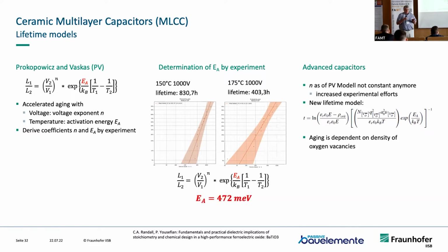And if you want to parameterize them, you have to do the experiments for 1, 2, 3 parameters. So 3 runs with different parameters to get a model out of this. And if you do this, or we do this as the industry does, there are more advanced capacitor models with more parameters. So to my understanding, there is no way to parameterize them as a standard routine for reliability methods. So I think we are at the edge where you really can use empirical models for lifetime prediction.